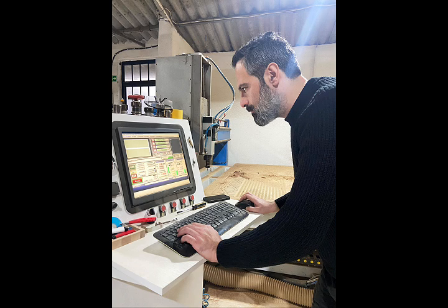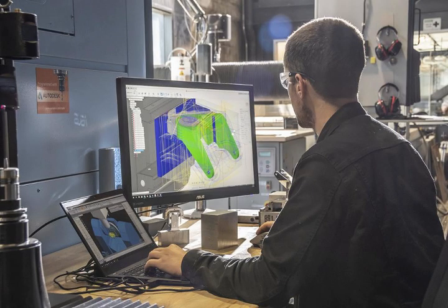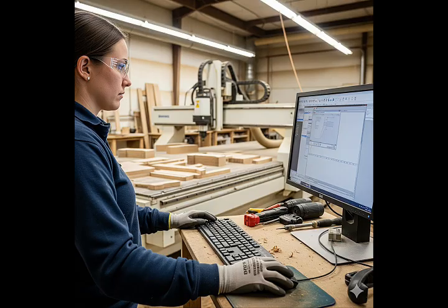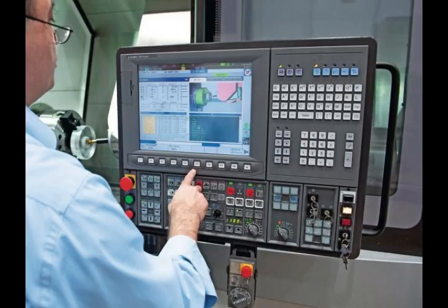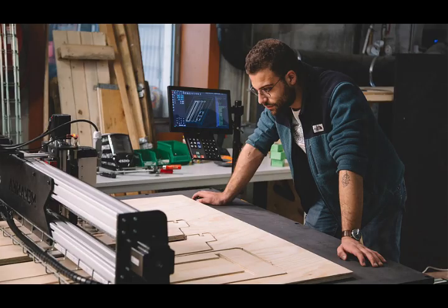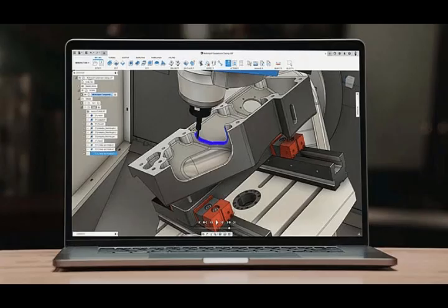How these parameters work together. One of the biggest mistakes beginners make is changing only one parameter. Imagine increasing spindle speed while keeping the same feed rate. The cutter now removes a much smaller chip. Instead of cutting efficiently, it begins polishing the wood. Heat rises dramatically. The opposite happens if feed rate increases without adjusting spindle speed. Cutting forces become excessive. Professional CNC operators always adjust spindle speed, feed rate, chip load, and cutting depth together.